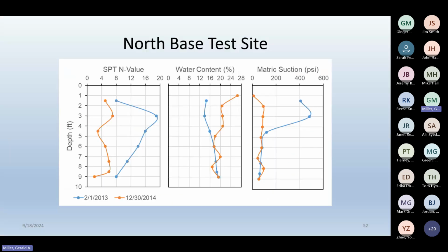Yeah, if you go close to the surface, you can see a significant difference between two different dates in matrix structure and water content. But the difference is very low for a split number. Makes sense? It doesn't necessarily make sense, but that's what the data says. I attribute that probably just to the natural variation in the soil. You know, you're averaging water contents from 3 different samples. You're averaging N values. Probably if we looked at each of the SPT profiles separately, it might make more sense.